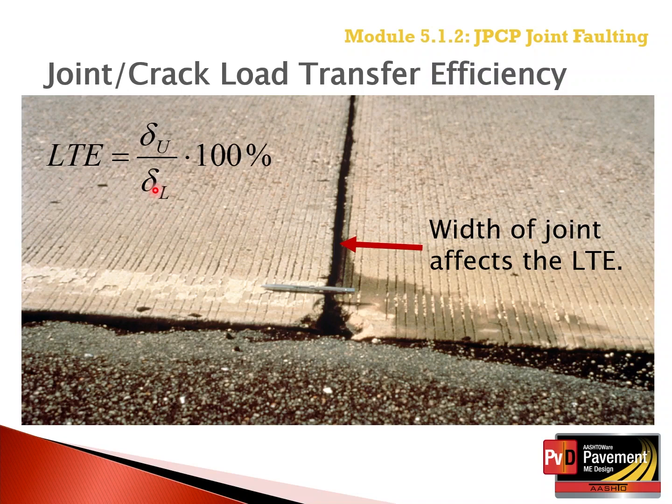In other words, the ratio of the deflections of the unloaded slab divided by the deflections of the loaded slab starts to decrease. So the load transfer efficiency decreases.